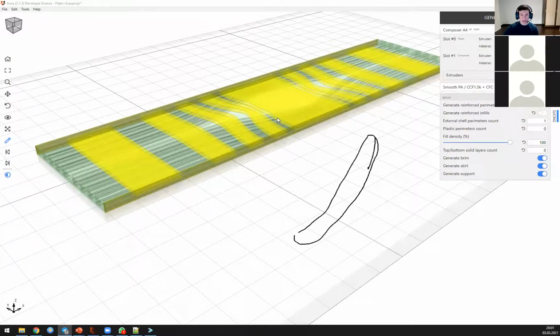And our experience shows that the result for isotropic material and result for anisotropic material will be very close. So if the remaining volume is a grid, then in this grid, all the ribs are working along this rib in tension, compression, bending, etc. And these ribs are not working in a perpendicular direction. So the result for anisotropic and isotropic topology optimization will be very close.